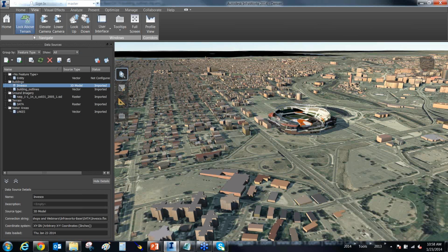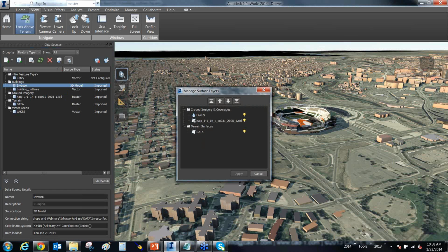And then the last thing I definitely want to show off is if you're going to be using multiple terrain-like layers, you've got a button inside of your data sources, and this allows you to organize and stack your terrain layers. Basically, it's who's on top wins. So you'll notice that I've got some move on top buttons, move above other buttons, etc. And this is also really important.